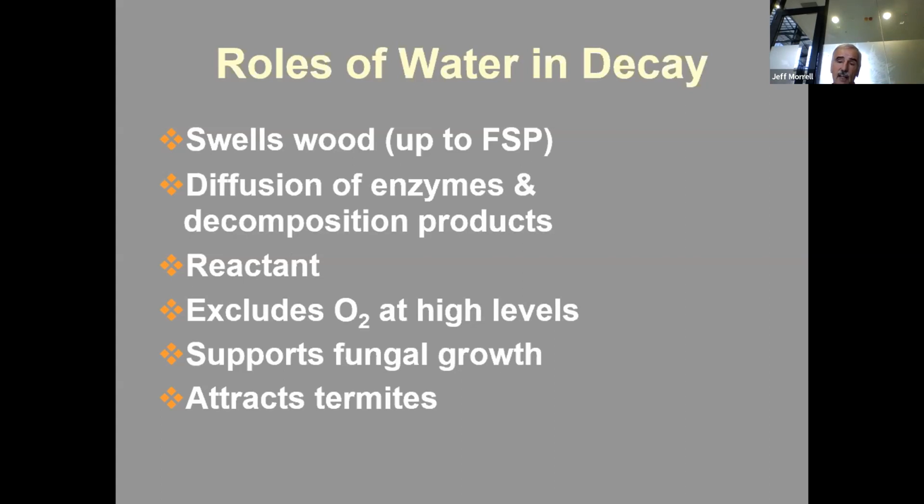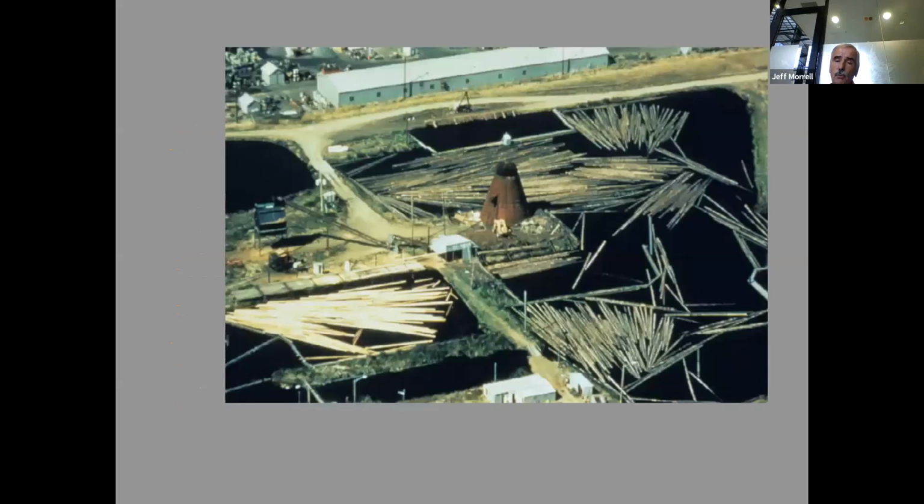Water is also a reactant. It's part of what we call hydrolysis, breaking down the cellulose and hemicellulose. So it's part of the reactions. If you get a lot of water, it excludes oxygen, so we'll talk about that in a second. It obviously supports fungal growth. It can also attract termites. If you have a lot of water in the building, that will tend to get more termites to move upward into the structure.